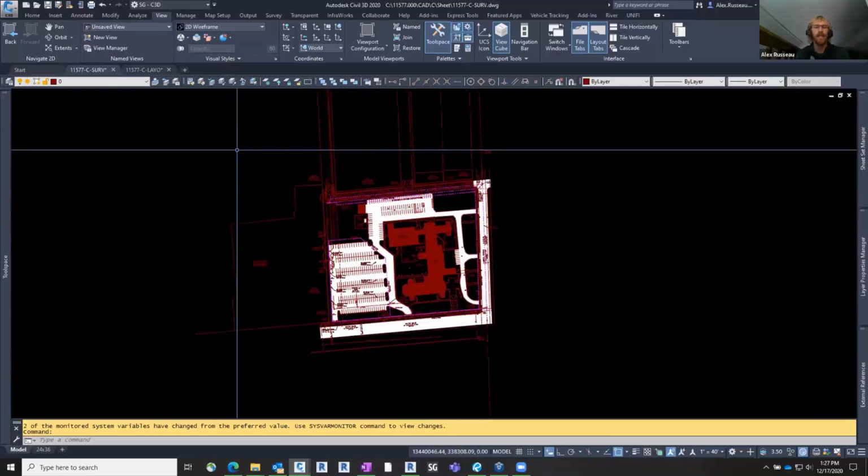The problem that usually happens between Revit and Civil 3D is Civil 3D has its own content that is native to it, and Revit doesn't quite understand it. I'm talking about points and surfaces and then pipe networks. Those are three things that are Civil 3D specific that Revit tends to struggle with. So if you were to purely link a Civil 3D file from the civil engineer directly into Revit, you're going to get all sorts of warnings. There's going to be a lot of issues with those files.